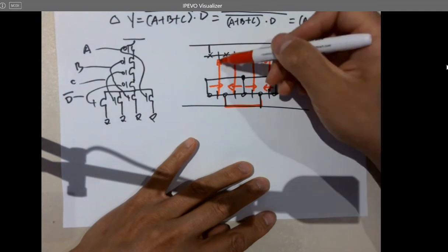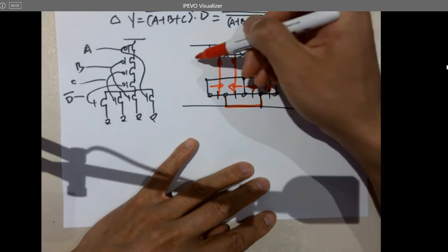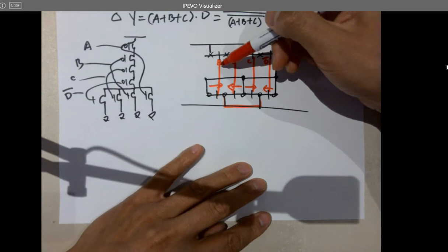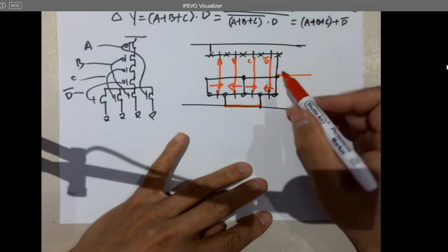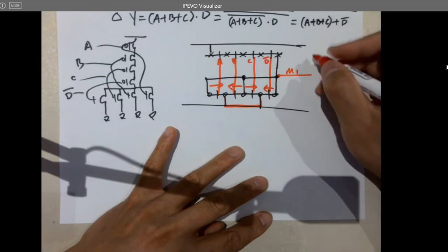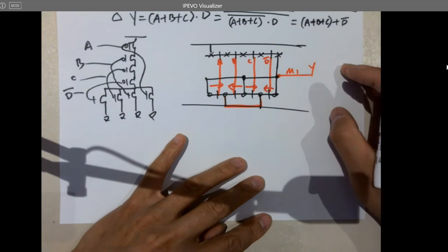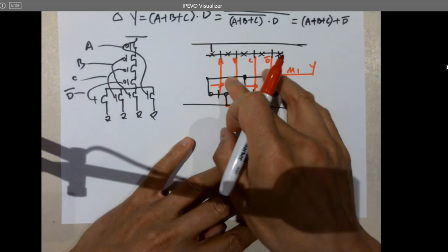Now you're asking, you have so many inputs, how to introduce this, or how to export the signal lines. But definitely this is the output, that's easy. You just drag a line in the layout, like a metal 1 layer, and just call it Y, right? Just name it as Y, which is fine. What about the inputs? They are all inside.